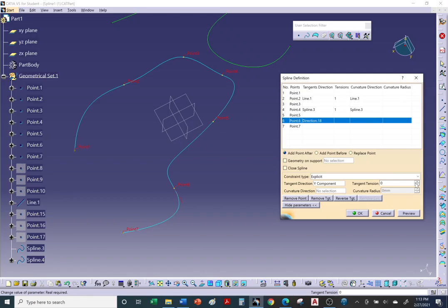Okay, I'm going to add tension to it. Increase the tension. Typically the minimum you want to use is 0.8. And you can go maybe up to 1.6, maybe 2. All right, so now for curvature, I'm going to right click and this time let's go in the X direction. Okay, so now it's trying to turn in the X direction.